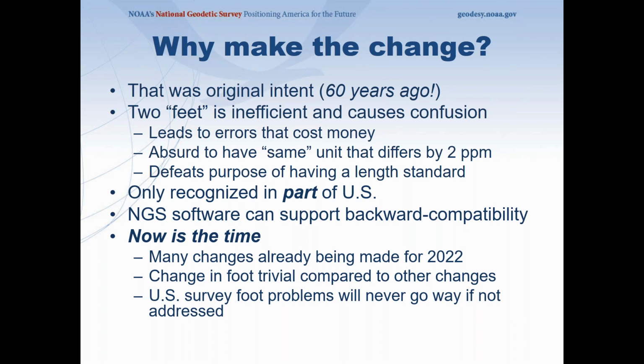And we know the survey foot problem is never going to go away, and if we don't address it, it won't go away. Some states will want to keep it, but they'll be able to handle that. But from NGS and the government, when they do a conversion, they're going to be using the international foot.